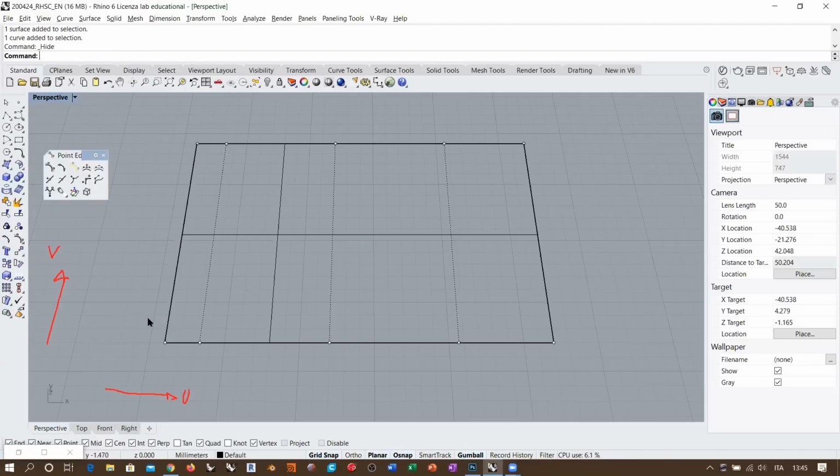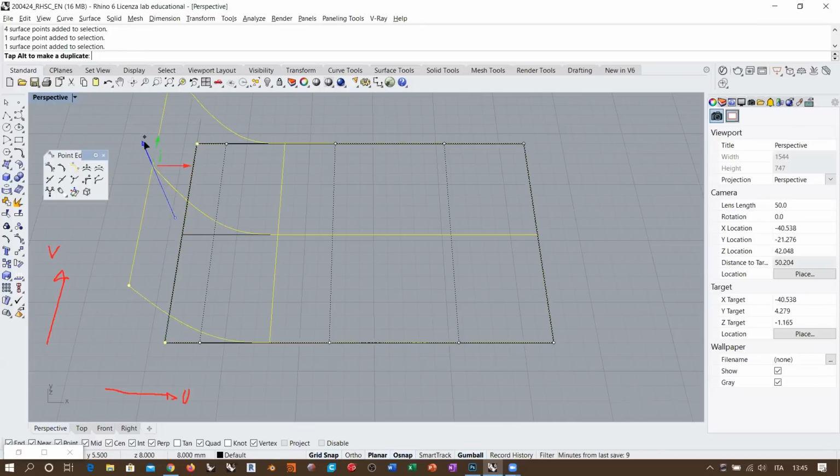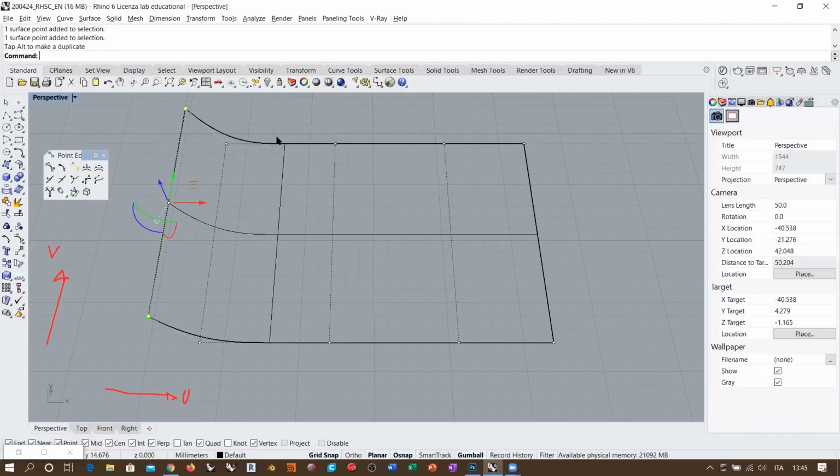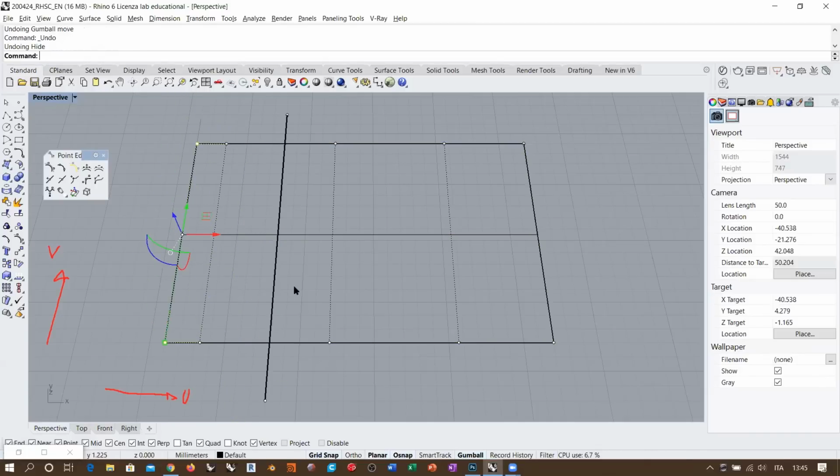So we have, in this case, 5 control points, because we know that 4 control points act on the first span, and the second set of 4 control points acts on the second span. So now the first line of control points will only affect the first span of my surface. So if I take this line of control points and move it up, I am only deforming the surface in the first span, so down to this isocurve that corresponds to my limit, okay?